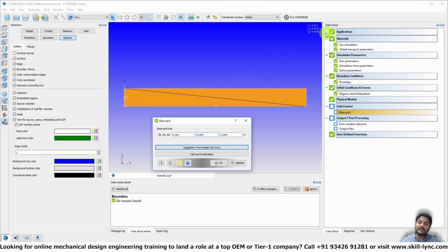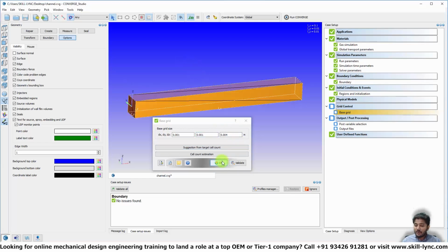So in this particular case, along y-axis, the dimension is 0.01. So if I need 10 cells, well, that's going to be 0.001 as well, correct? So that's going to give me 10 cells, and along the z-axis I really don't care, because that's the direction in which the flow is going to be ignored, in other words made 2D, right? So let's just click on OK now.